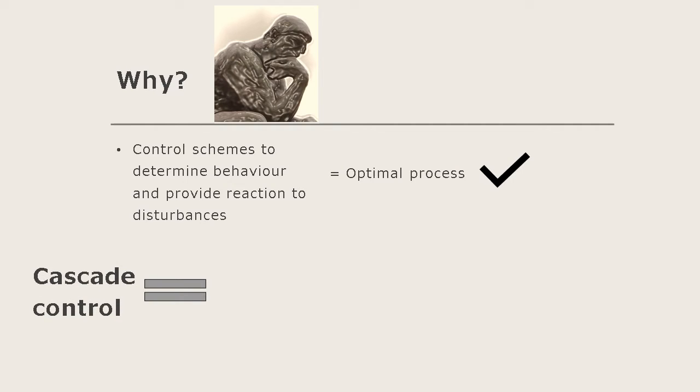Cascade control is mainly used to achieve fast rejection of disturbance before it propagates to other parts of the plant. It is also used for processes with slow dynamics such as temperature, level, humidity, and others. Cascade control can be applied in a useful way to any process in which a measurable secondary variable directly influences the main controlled variable.